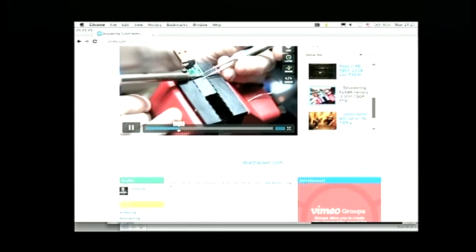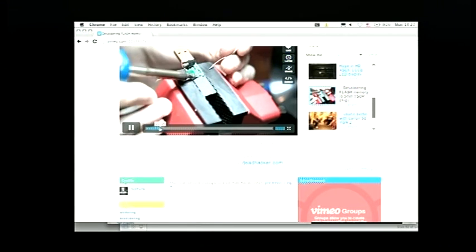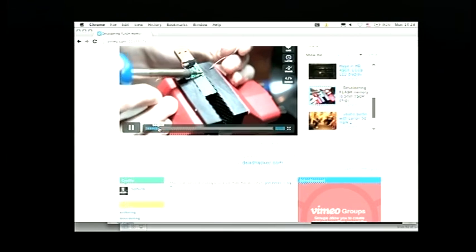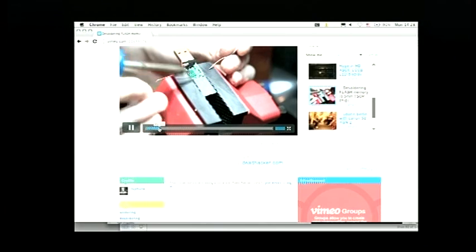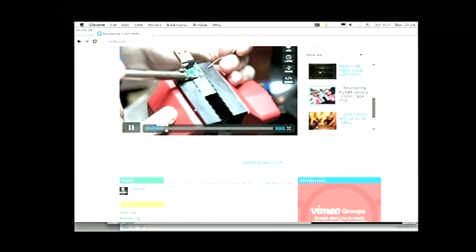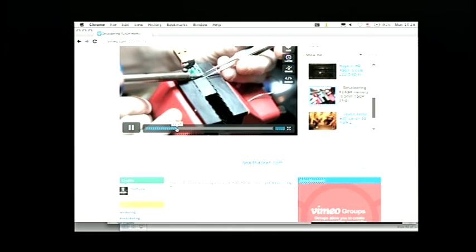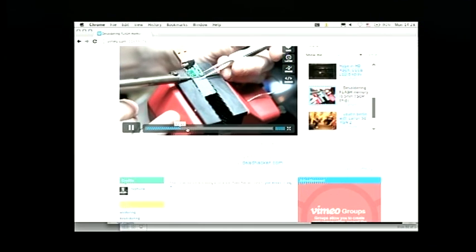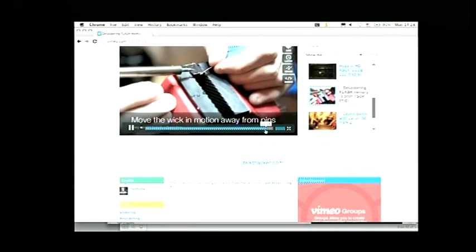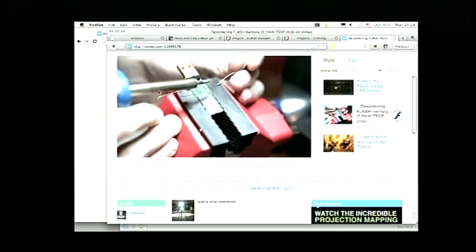Great. Okay, so basically I've applied a bunch of solder to one edge. What this allows is once the solder is evenly applied across all of the pins, then applying heat to one point makes all the solder fluid, so that allows you to pick it up. So at some point I just apply heat and start to apply just a small amount of pressure underneath, and then it sort of pops up. That's it. So you do this to both sides, and then you clean it with solder wick at the end, and then you're done. So it's not that difficult.